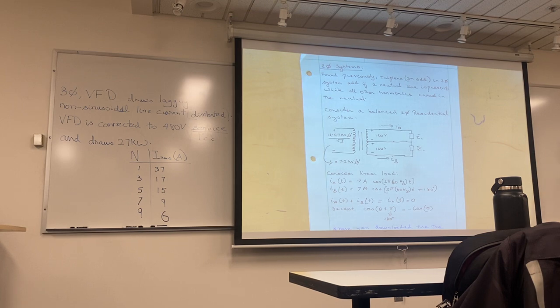Quick question. I keep saying multimeter and voltmeter. How do you measure these voltages? Have you seen a multimeter capable of 12,000 volts? No. Tell me about it. Not today, I'm running out of time. But the way you do it, I'll give you the 30,000 foot view: you will step it down, and we'll see what a step down is. Essentially, you're going to reduce this voltage, I think to like 120 volt AC, and then we have equipment that can measure 120 volt AC.